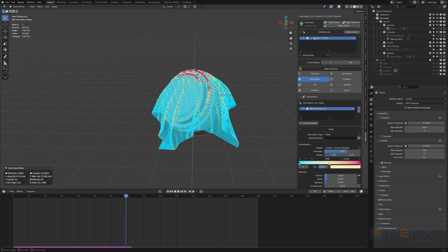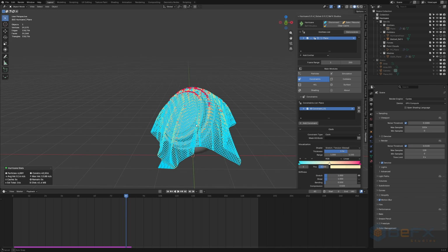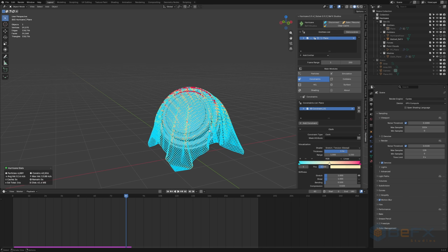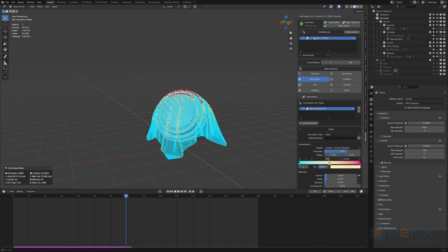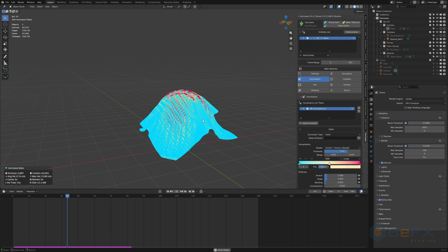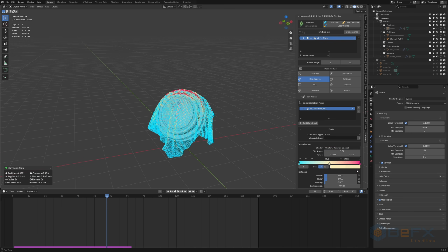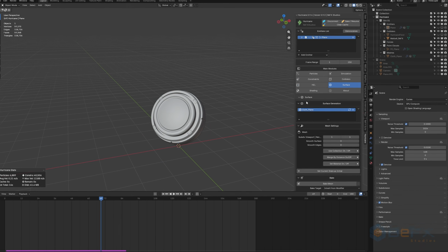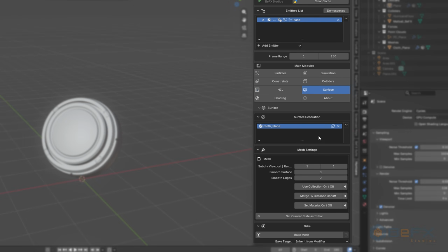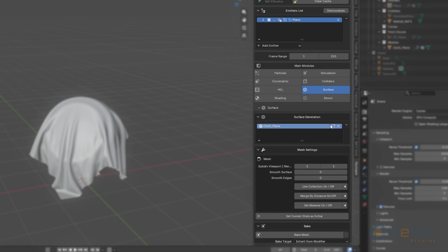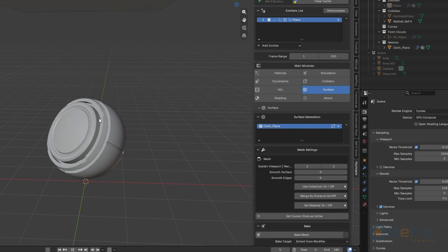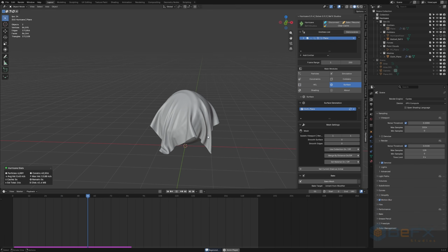We can toggle individual visualization for each cloth constraint type to inspect them separately with greater clarity. Let's go back to working with the mesh display. When re-enabling it, it might not show up immediately in the viewport if we have tweaked constraint values, as the mesh needs to refresh its structure. To fix this, we simply click the Update icon, Update Mesh, to regenerate it.